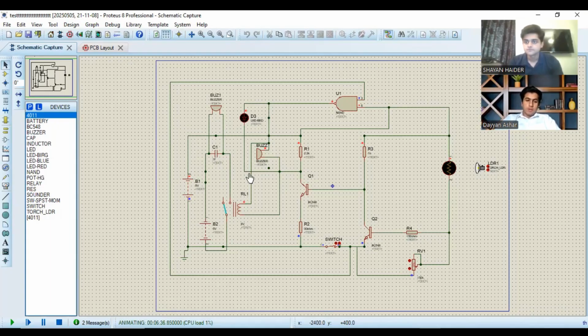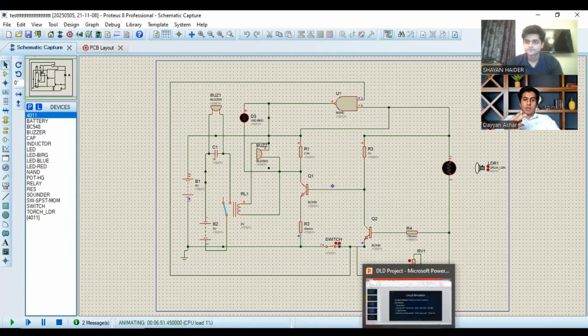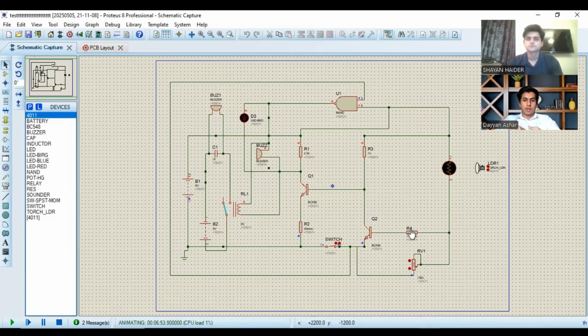Yes, sure. So we have added a capacitor basically so that when buzzer one is activated, in the meantime the capacitor is charged. So when buzzer one deactivates, the charged capacitor will make buzzer two activate. So basically we have two buzzers. Buzzer two is activated through the capacitor. And we have done this to continuously make the buzzer sound whenever there is an optical breach.